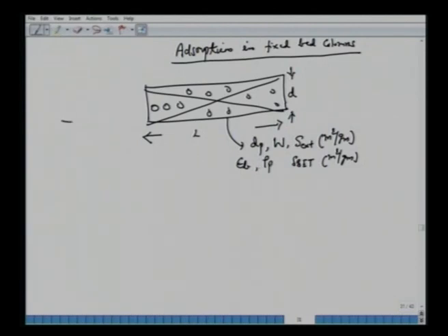And here we bring in contact, or we challenge, this packed bed, which is initially clean, fresh, with no solute inside, with a certain level, let's say 1 here, or C in. Certain flow rates, Q in standard liters per minute for the gas, or for the liquid we have liters per minute.